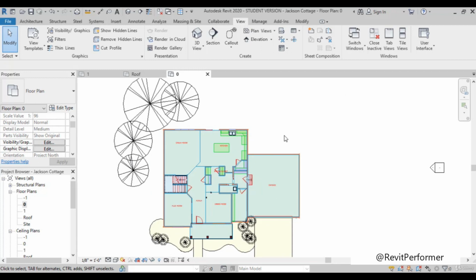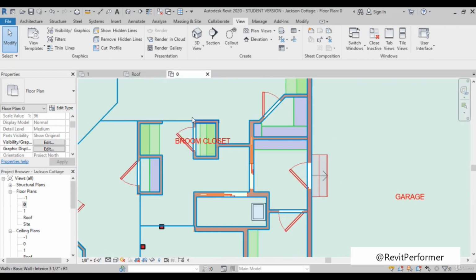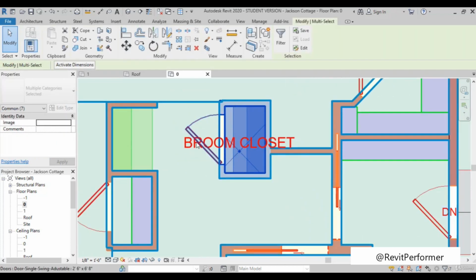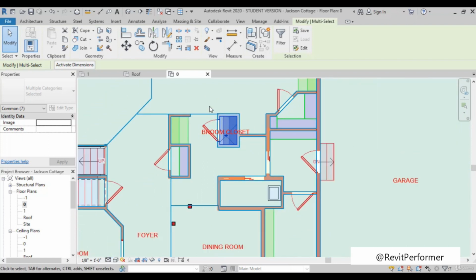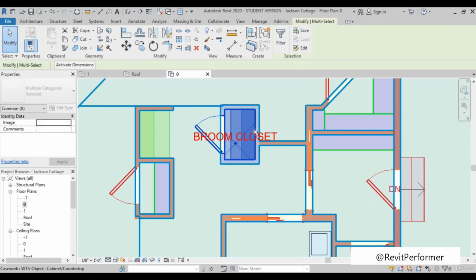Okay. So this is like if you select this bedroom closet. Just click it and select the solid way. This selection only happens when you totally cover all the parameters of this bedroom closet. So you can see these are selected. These doors are not selected, because when I select this, only half the door is covered. You have to cover all of this for it to select. If I cover all of this door also, it will select the door and this bedroom closet.